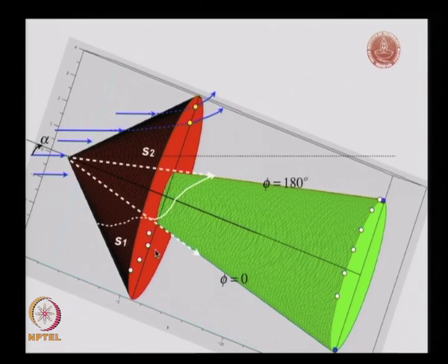Okay, that's it. Now obviously, we will have several other streamlines. If I do that, let us just look at this space here. You have these particular streamlines. All of these are going through the shock wave, and then they curl around from the bottom of the cone up to the top. The bottom is the windward side and the top is the leeward side.